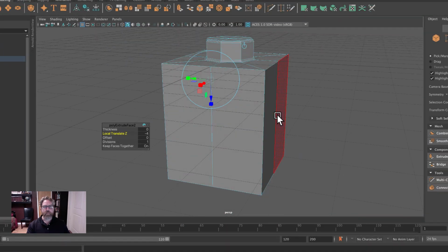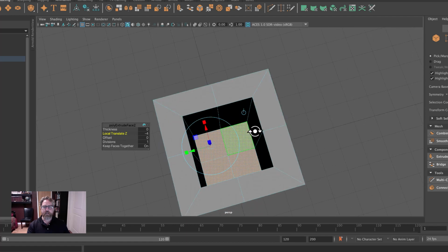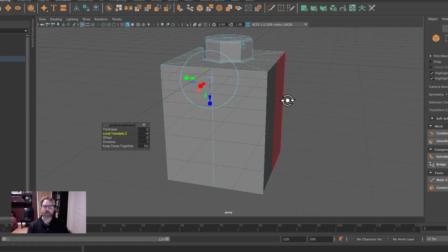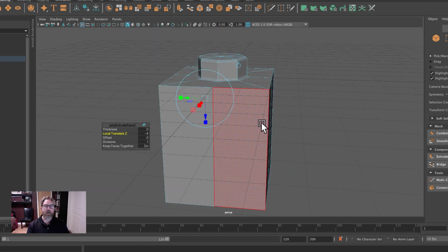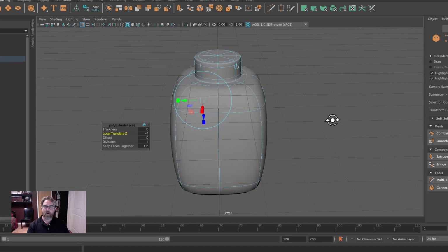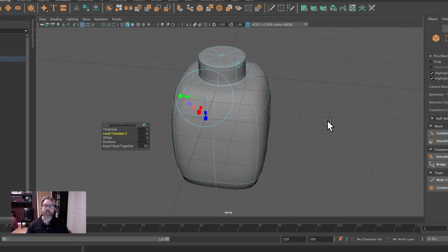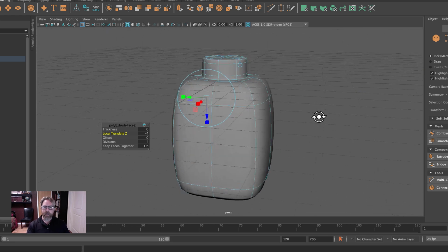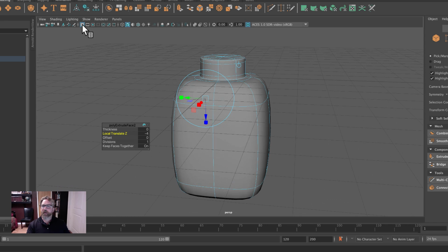If you look at toy bricks, you can see that there's an indentation beneath each of the pegs. But for today, the final thing that we'll do is just bevel these edges so that when we hit the 3 key, it maintains its hard edge. And hitting the 3 key is a preview of what happens when we subdivide, which is how we'll end this model today. I'm also going to go ahead and hide my grid since we no longer need it.